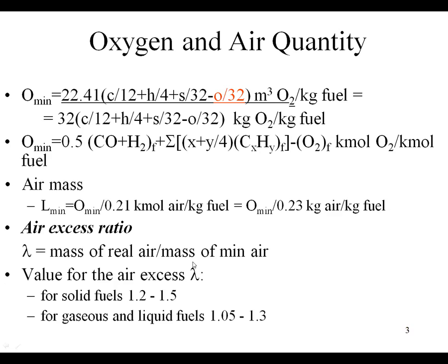So normally this air excess ratio is over 1. But it must be limited, because oxygen is not coming alone from the air. It is accompanied by nitrogen. And nitrogen can, at high temperature, react with oxygen, producing a very harmful pollutant, NO or NO2. This is real. It happens also in the atmosphere.